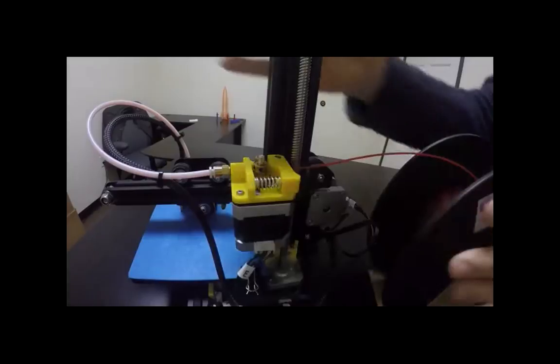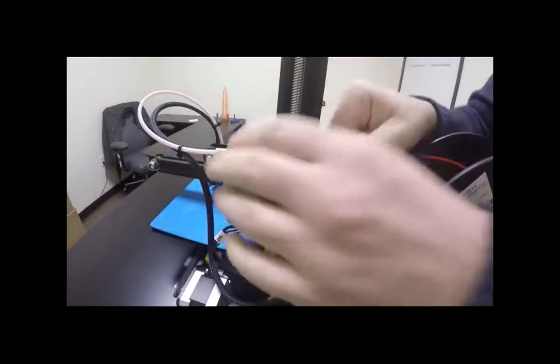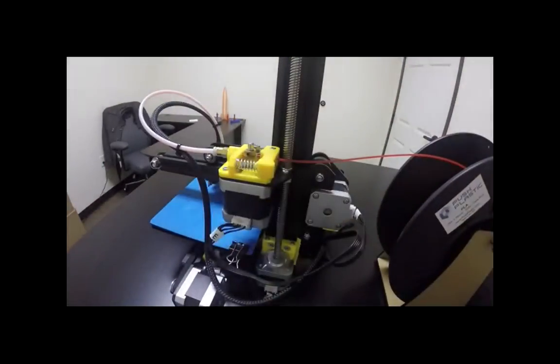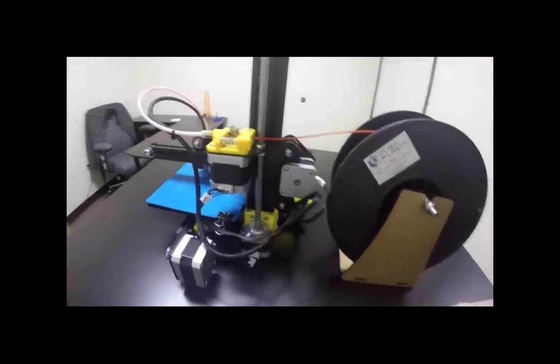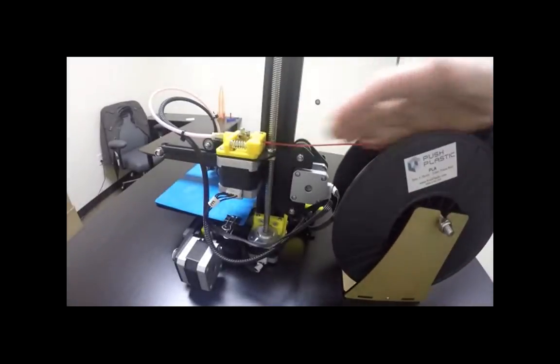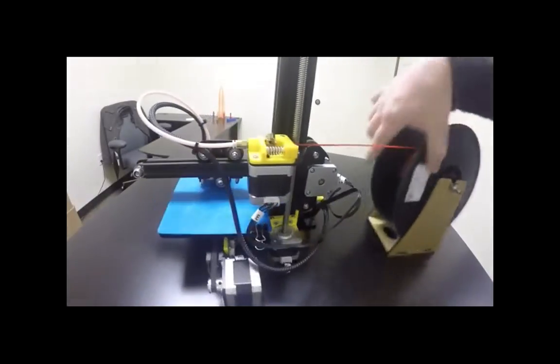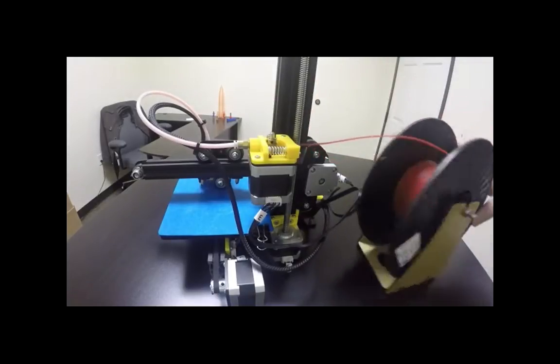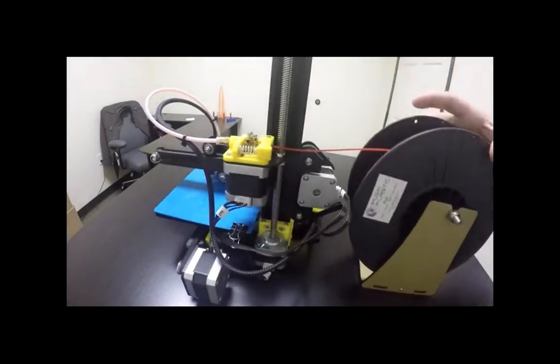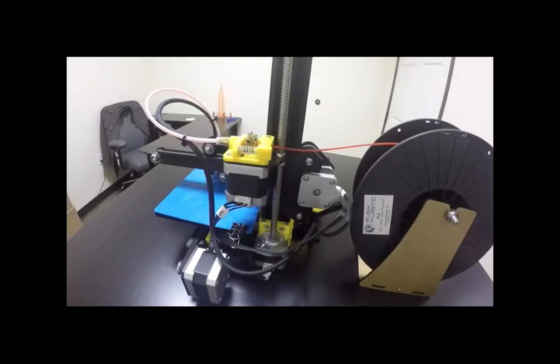All the way down to the end. And then when you push it all the way to the end, then it's all the way loaded. And then you always want to make sure that the filament feeds in straight like this too, so you have it lined up so it feeds through. Because if it's over here, if it's pulling around the side or something like that, that can cause a lot of tension and it can cause things to jam up. So let me know when you get that all the way fed through.